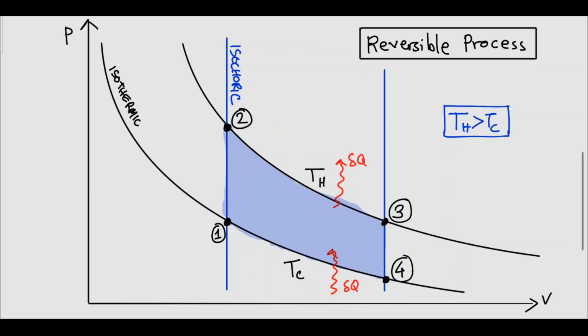Now we are going to talk about the phase diagram of the Stirling process. And it looks, as you have seen, a bit different as compared to the Carnot process. You still have the isothermic parts of the plot, but instead of the adiabatic parts of the plot, you now have the isochoric ones, which are given by the blue lines. And you again have 4 points, which we will also be looking at with an example.